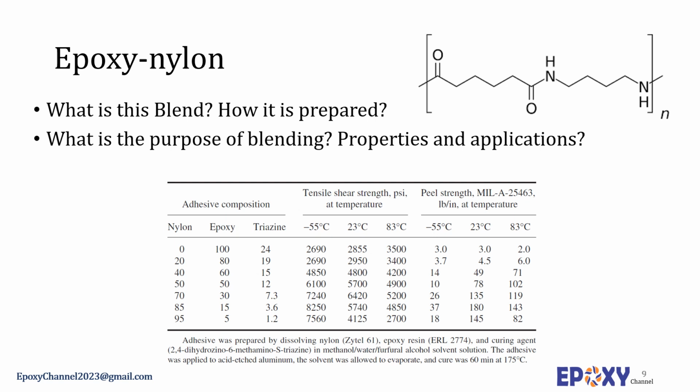The nylon constituent provides high tensile shear strength as well as high peel strength. Suitable catalysts are dicy and aromatic polyamines. These adhesives have useful properties at low temperatures, but only moderately good properties at high temperature.